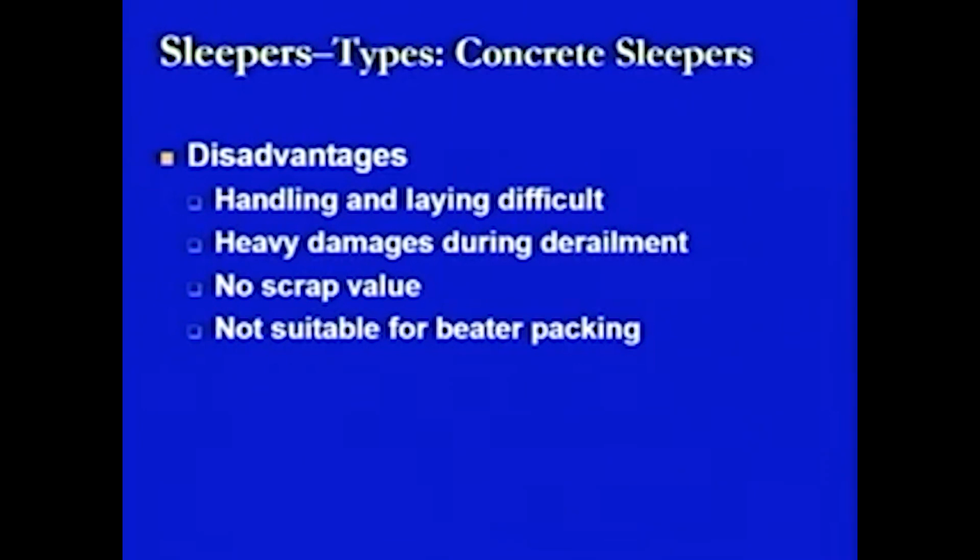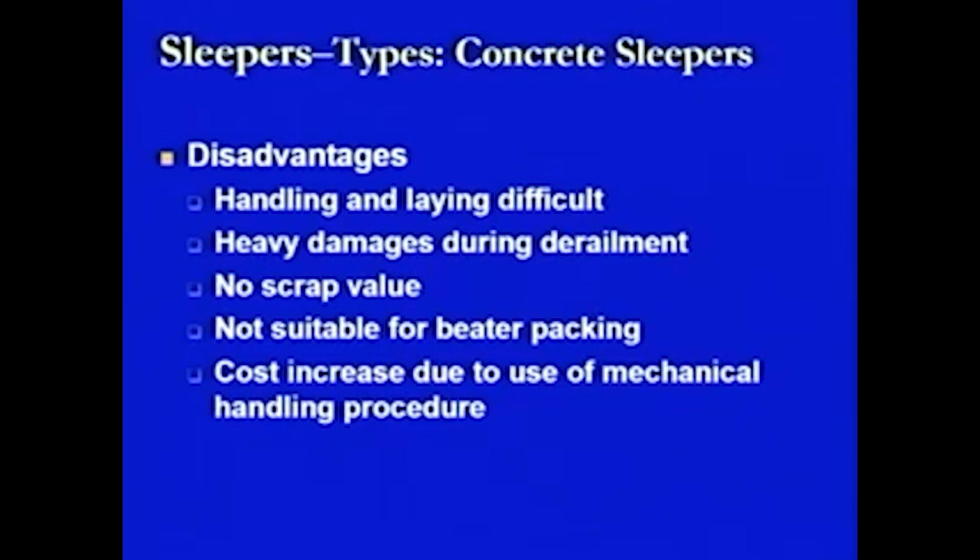They are not suitable for beater packing. Beater packing is a sort of mechanical device where we have to beat the ballast cushion which is provided on the sides of the sleepers. That is the packing of the ballast. It is not suitable for that, because if the beater hits the concrete sleeper, the concrete sleeper may get damaged.